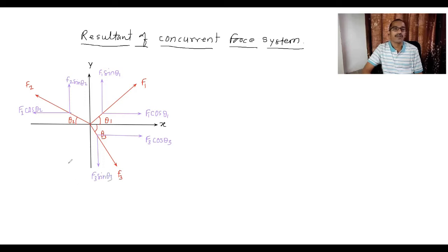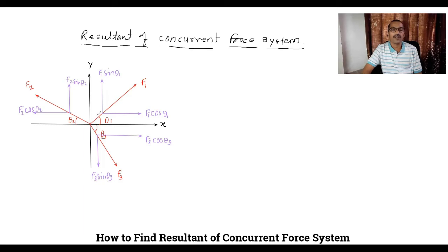Now, when we find the resultant, it means that all the given forces acting on a body, whatever the number of forces in the force system, are replaced by a single equivalent force. The single equivalent force is called the resultant. For a concurrent force system, as inclined forces are given, we resolve all the forces and add all forces in the horizontal direction with proper sign convention.